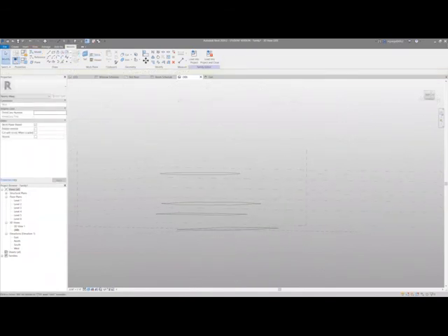Yes, we got it. All right, now we're gonna create the form. And boom. A lot like Rhino with Boolean forms, in Revit you have solids and voids when it comes to massing.